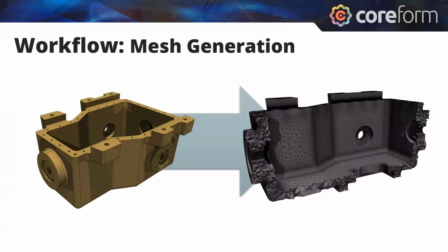And then I mentioned that we have mesh generation as the next step. This is really just taking whatever your CAD geometry is, and you've got to put a mesh on it so we can discretize it, so we can solve our partial differential equations on it. Even if it's just a simple elasticity, it's still a differential equation that we need to have a discretized model.